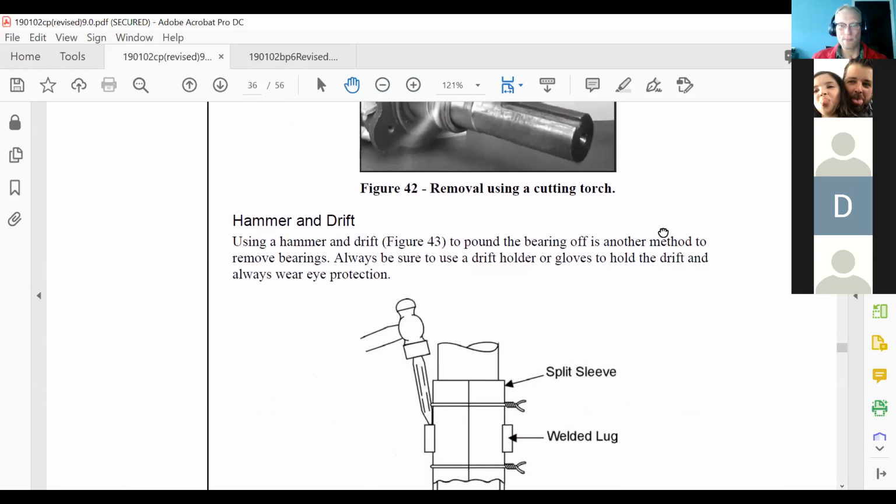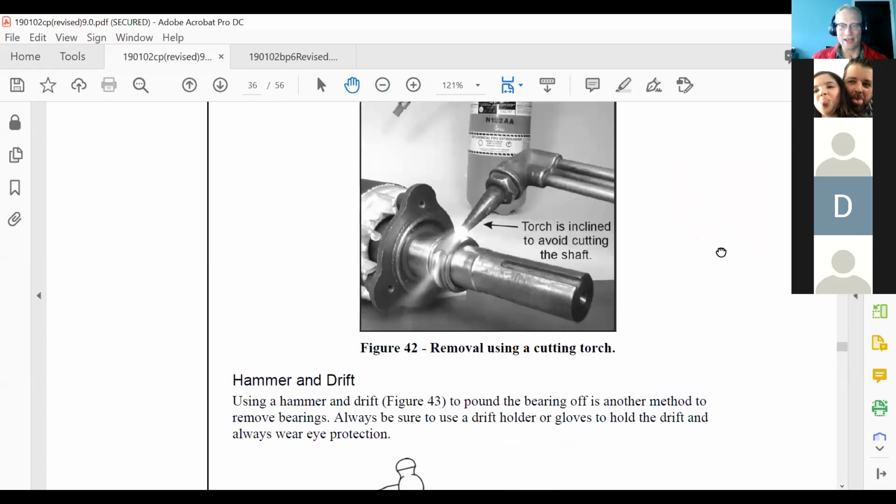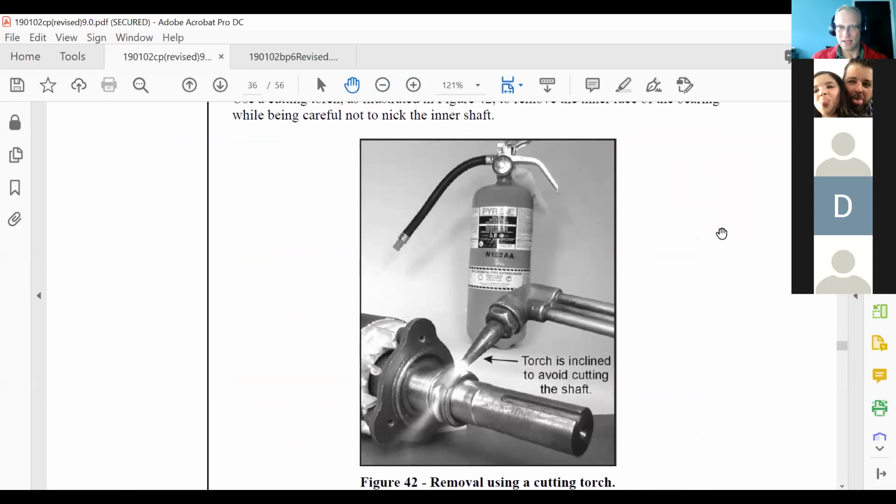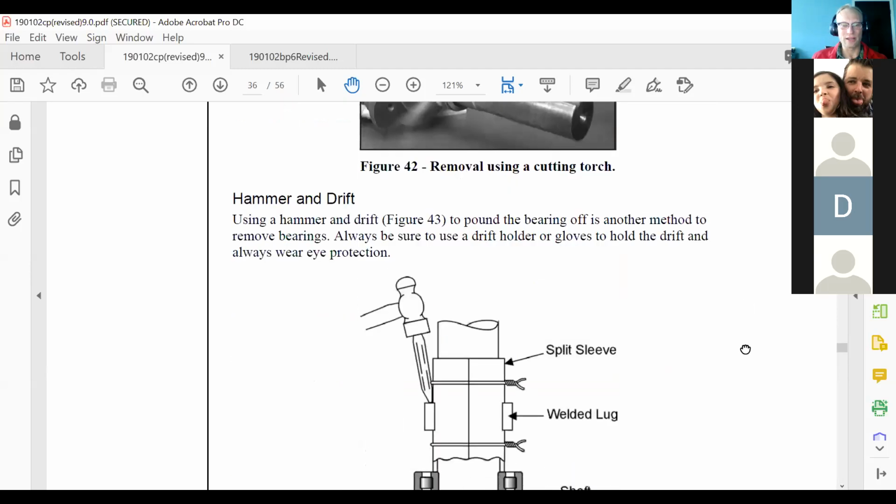They're supposed to be monthly inspected. Yeah, they are. And you know what? If you use a fire extinguisher, don't not tell anybody. Please tell somebody so they can get a new one, figure out why the fire happened, what you could do to prevent it in the future, and also get a new fire extinguisher, okay? Don't hang the old one back up, because if somebody isn't really checking, they might think, oh, there's a fire extinguisher hanging there. It's a good one, because in a panic moment, that's not the time you want to find out that it's not good.